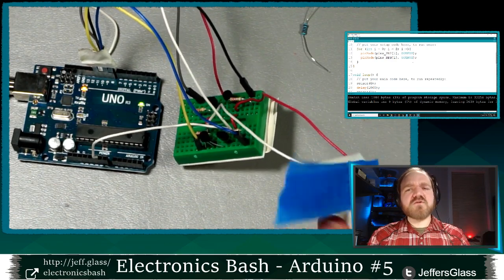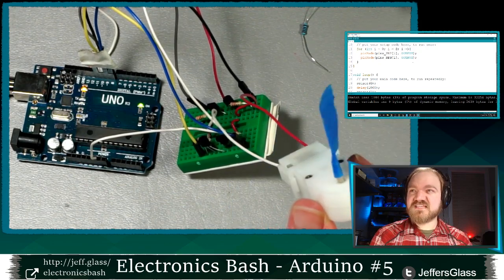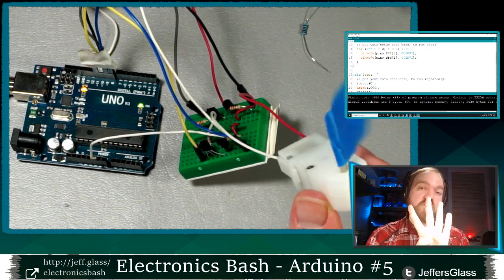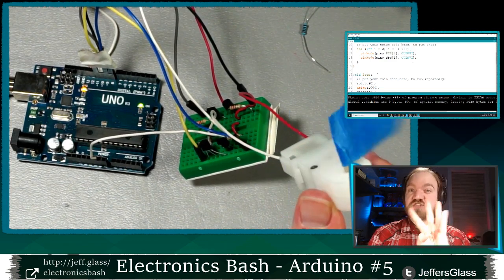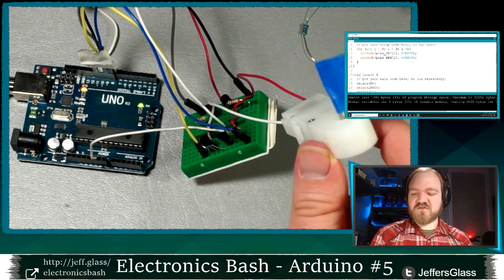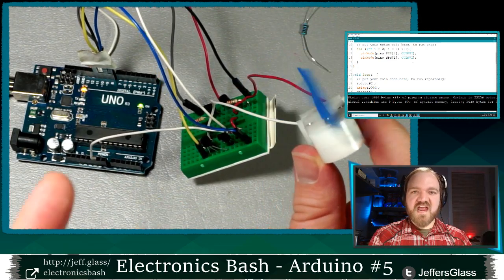So if you have a multicolor LED, I know Megan Snowder last week was asking about red, green, blue LEDs. Those often have not 2 terminals, but 3 or 4. So you don't necessarily have to reverse current in them. You just have to choose where the current is going. So an H-bridge might not be applicable for that. But for driving a motor or doing something where you have to reverse the current, an H-bridge is the circuit for you.